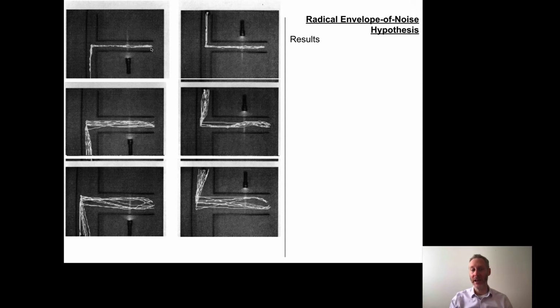When the light was on the Khepera's left, the Khepera would consistently turn left. You can see they put a little LED on the top of the robot so they could record in a darkened room the trajectory of the robot. And then if they took the same evolved controller and ran that controller multiple times on the physical Khepera and put the light on the right, the Khepera consistently turned to the right. You'll notice the difference between this pair of images and this pair of images is that the T corridors themselves are wider. So the robot is also robust to changes in its physical environment.